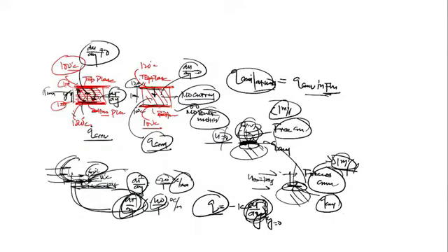I had told you that when the fluid is in motion, the older fluid is replaced by newer fluid, comparatively lower temperature fluid. It means the high temperature fluid is replaced, and every time the surface is exposed to new fluid whose temperature is relatively lower than the previous. Listen, when the fluid is in motion, every time the surface is exposed to new fluid, as compared to when the fluid was at rest. Yes or no? And when the surface is exposed to new fluid, there is always a velocity gradient, and that causes the temperature gradient.